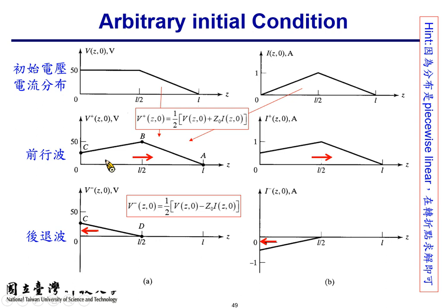the problem. So providing that you don't have loss on the transmission line, and because the terminations are lossless as well, the signal will remain on the transmission line and cycle in the transmission line for a very long period of time. But the truth is, because of the loss on the transmission line, the signal for a realistic transmission line shall bounce back and forth between the two open ends several times, but it will die out eventually, due to the loss on the line.